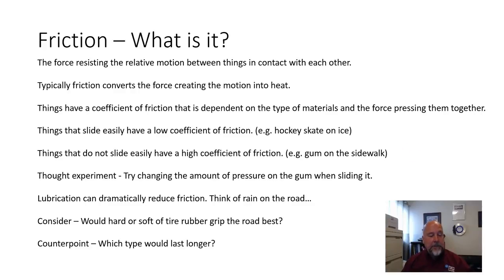So, things to consider. Would a hard or soft rubber tire grip the road best? If you think about that for a second, that would be equivalent to asking the question about either the hockey skate or the gum. The hockey skate doesn't grip the road because that interface has a low coefficient of friction. The gum, however, would stick really well. But which one would last longer? Fact of the matter is, the stickiest tire may not be what you want on your car. You may not want the absolute best traction because it may tend to wear out in a big hurry. You don't want to buy new tires every 2 days.